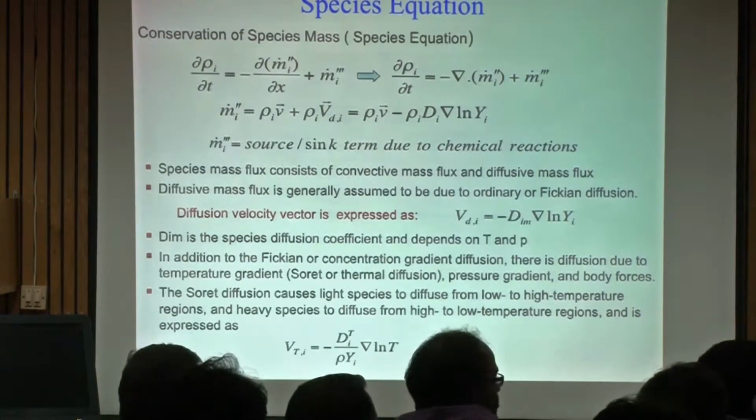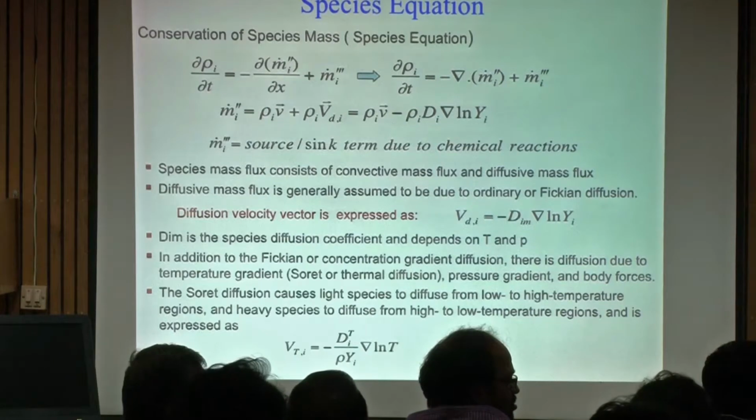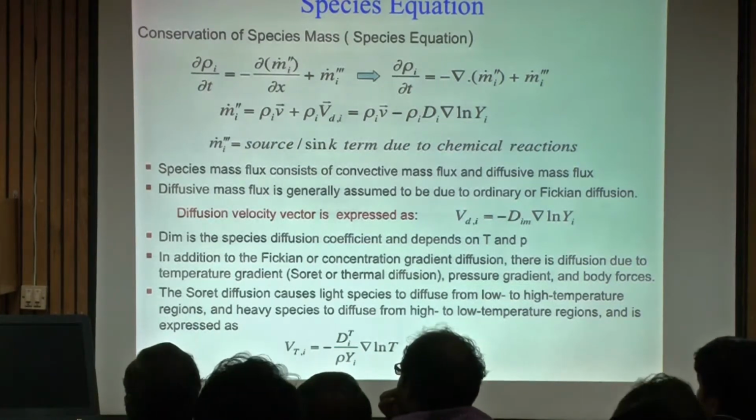Sir, what is the physical significance of this conservation form and non-conservation? No, these are two different ways of writing. You know, when they use CFD, we use a finite volume approach to discretize the differential equations. So if you use the conservation form, then they make sure that the momentum is conserved. There's no extra source appearing due to numerical method. Okay, so there it is meaningful.